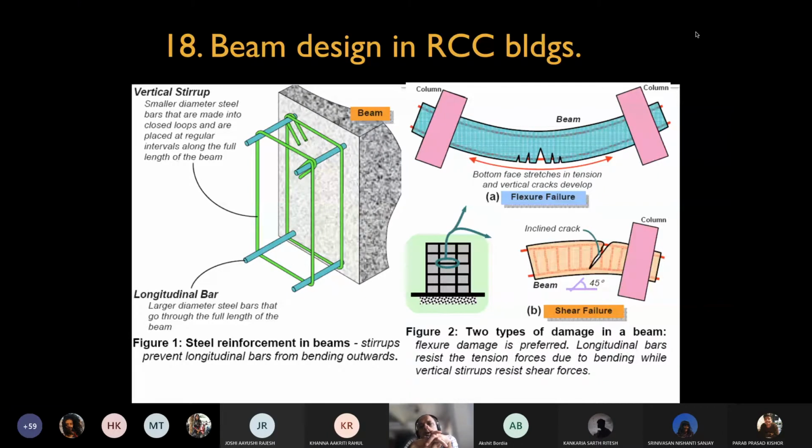and the whole thing will collapse. Now in Pune chambers, what happened was that the first slab collapsed. The lower slab was obviously not designed to take more load than its own self weight and the live load. The upper full slab came down suddenly, and it was impactful. It did not just land softly onto the lower floor.